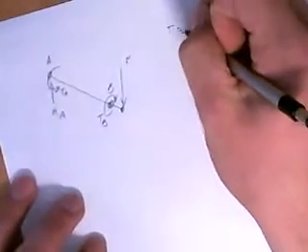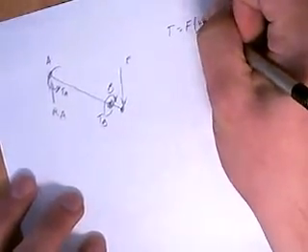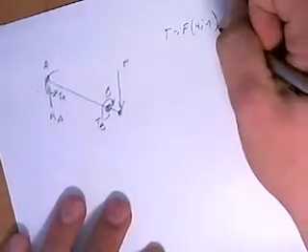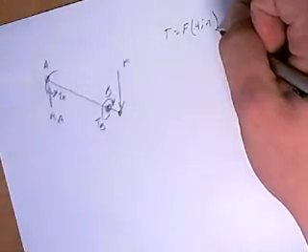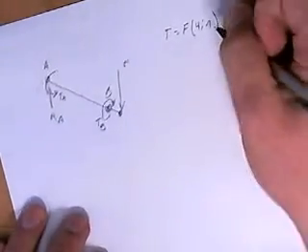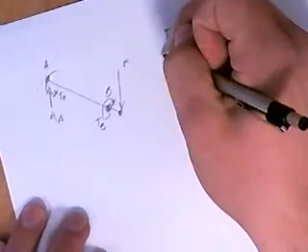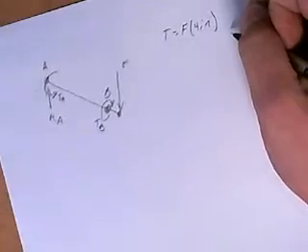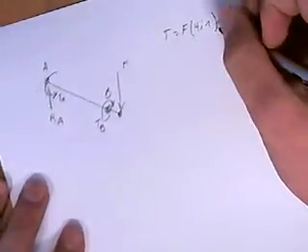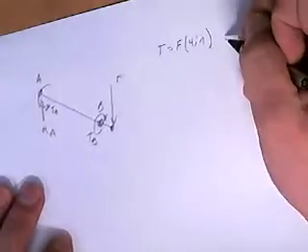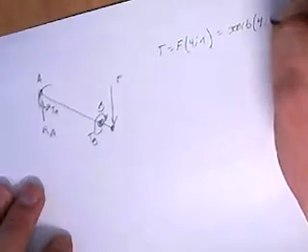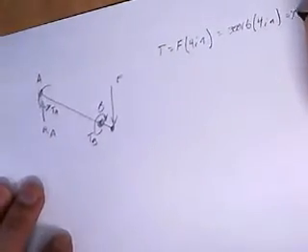Alright, so the torque is equal to the force times 4 inches, because the force is normally out here 4 inches away. If you want to go back to the video and draw out that picture, or screenshot it so you have something to look at, go ahead. That is equal to 300 lb times 4 inches, which is equal to 1,200 inch-pounds.